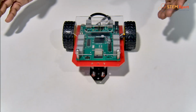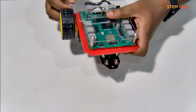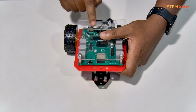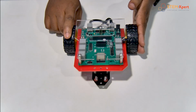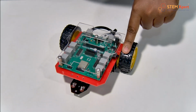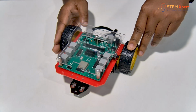For making a right turn, what did I say? This tire has to move backward. So I just want to make sure where this tire is connected. This tire is connected with 19 and 15, which means it has to make 0, 1. Just keep in mind 19 and 15 has to make 0, 1. And the left side motor, which I have connected with 25 and 26, has to move forward, right? Forward means 1, 0. We did that before. Just keep in mind 25, 26 as 1, 0 and 19, 15 as 0, 1. Then it would work perfectly.